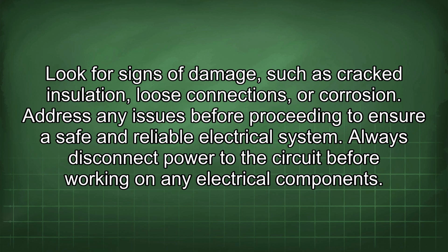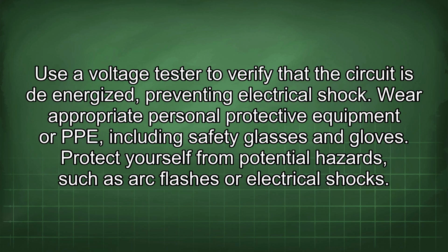Always disconnect power to the circuit before working on any electrical components. Use a voltage tester to verify that the circuit is de-energized, preventing electrical shock. Wear appropriate personal protective equipment, or PPE, including safety glasses and gloves. Protect yourself from potential hazards, such as arc flashes or electrical shocks.